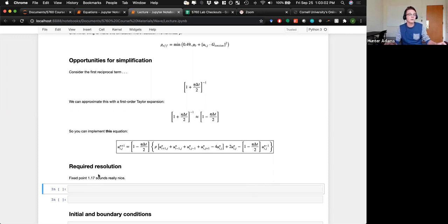The other nice thing about using 18 bits is it allows you to exploit the 18 by 18 hardware multipliers that are on the FPGA. So you can experiment with this, of course, but I recommend 1.18, which means that the amplitude of any node on your drum cannot exceed ±1, or you're going to overflow your drum.